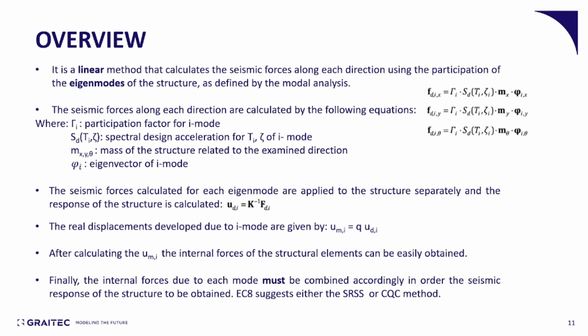A quick note here: it is important to combine in the end, which means that the SRSS or CQC method needs to be applied to the final product, the internal forces, for example, not to intermediate products, for example any parameters that are calculated during the process. Otherwise, the results will not be accurate.